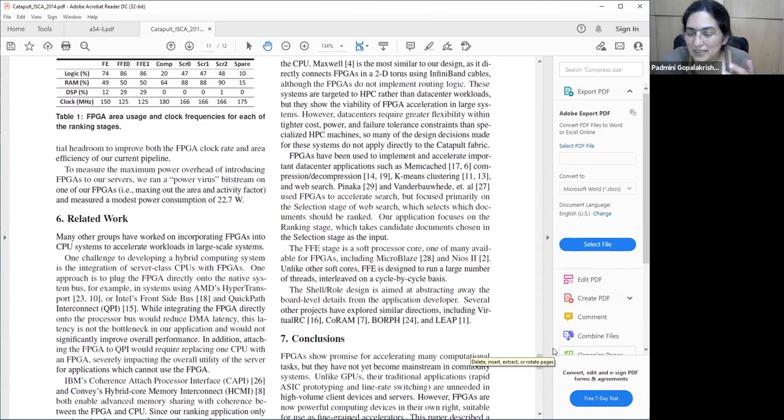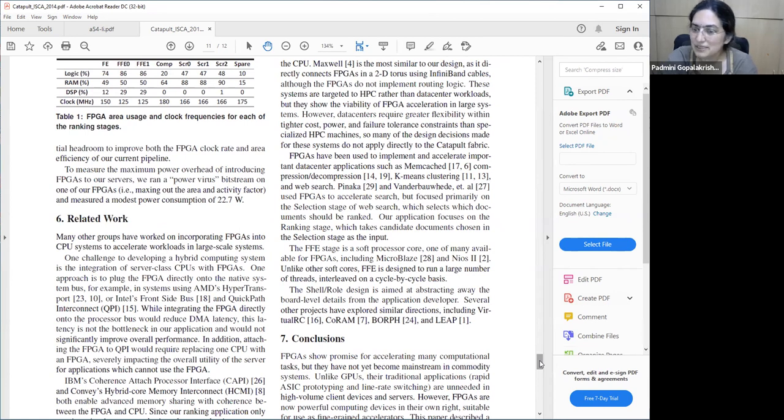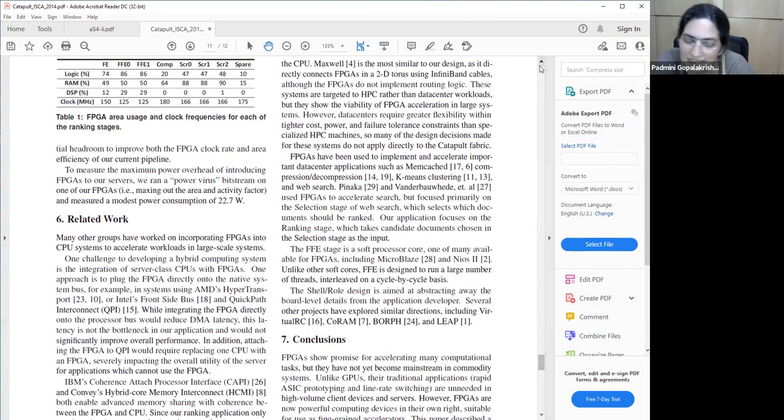You can, if you know your architecture very well. We know of customers who, for example, may hand place DSPs or memory to improve performance, or hand constraints. So there are a lot of tricks for squeezing performance. It does get harder as your utilization increases beyond a point. Typically 70-80% is that point. Okay.